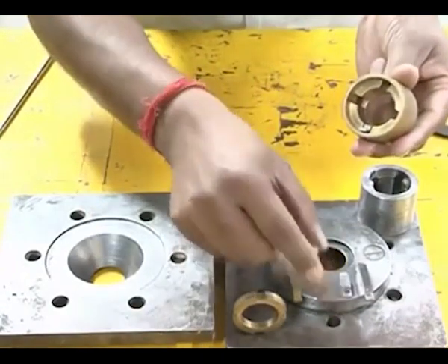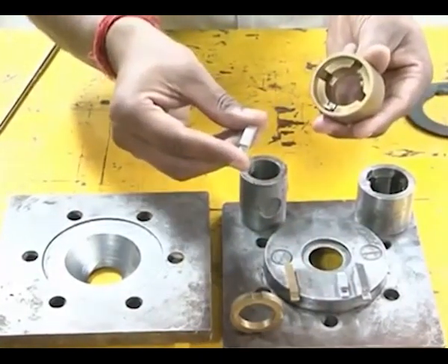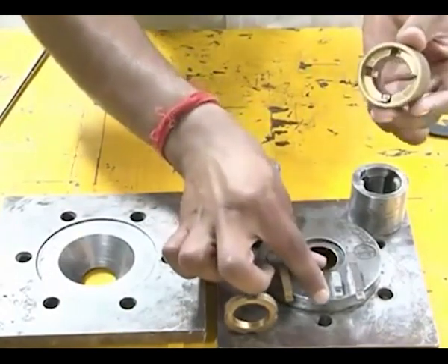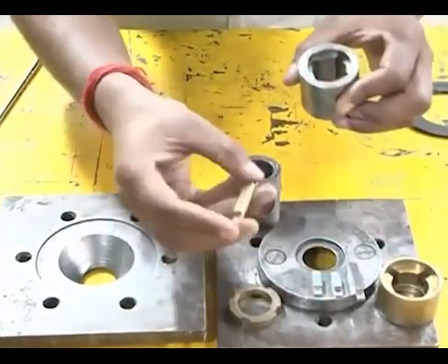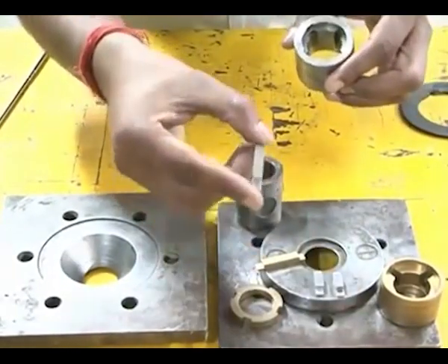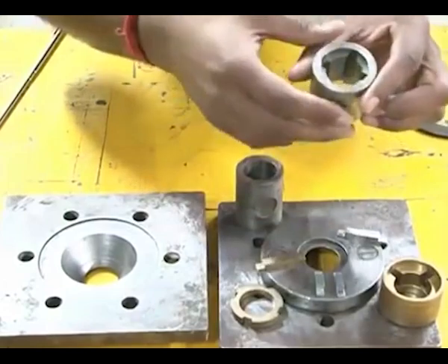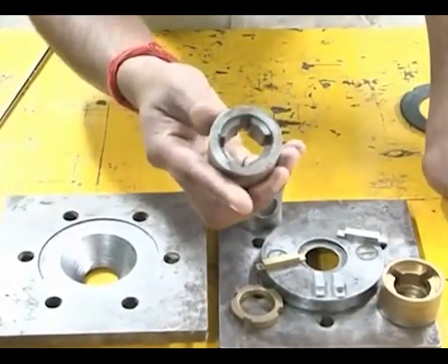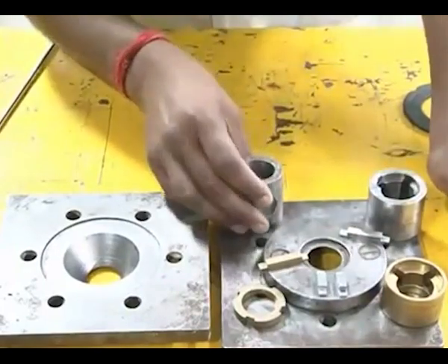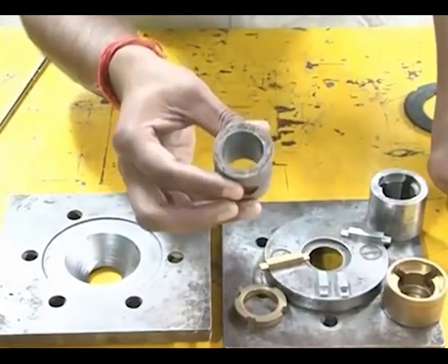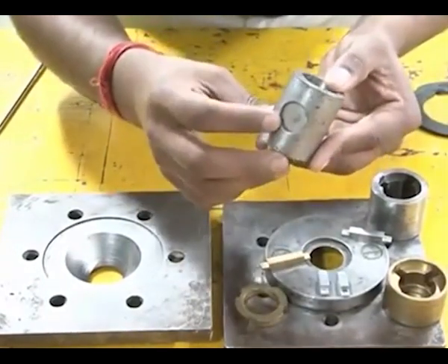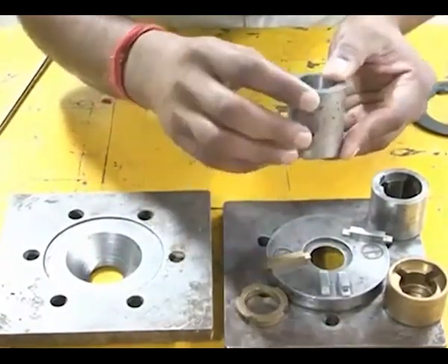And similarly, all these are the aluminum alloy and silicon carbide metal matrix composites, and we have also finished the brass workpieces as well as stainless steel workpieces. For this you require the special work fixture, that is this one, and we have also finished the cylindrical workpieces, and we have also measured the online surface finish measurement using acoustic emission sensor.